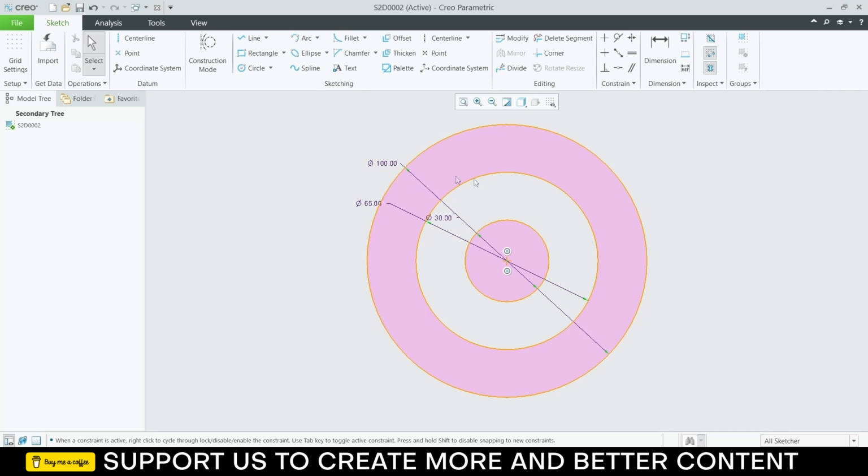So now I want to convert this line into a construction line. So how can I do it? Select this line. You can see this pop-up arrives. So click on this construction or you can press Shift plus G. So this line has now become a construction line and it is quite convenient to use.